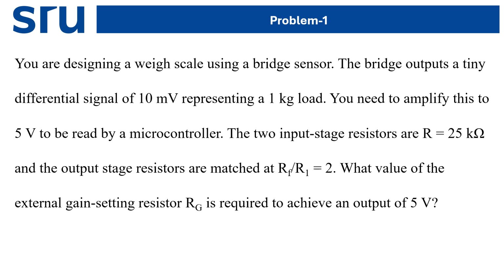So one good point here is that 10 millivolt is the input differential signal, which of course represents 1 kg of load. Now it is asking that you need a 5 volt output, which is to be fed to the microcontroller.